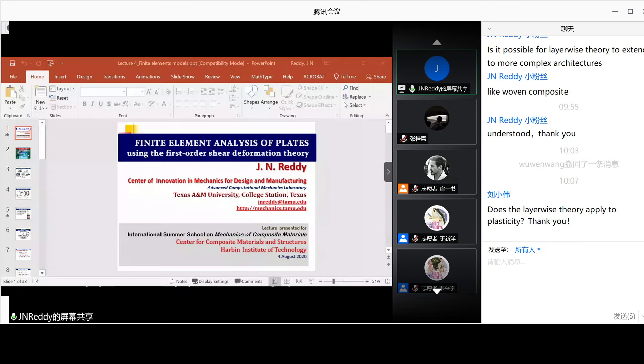If these are equations of motion, meaning time-dependent problems, we do it in two stages. One stage is called the semi-discrete finite element model, where we take care of the spatial approximation. Then in the second stage, we include time approximation and make the final fully discretized finite element model.